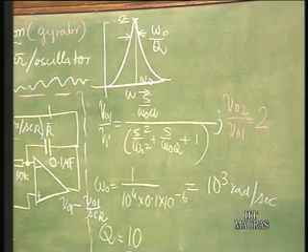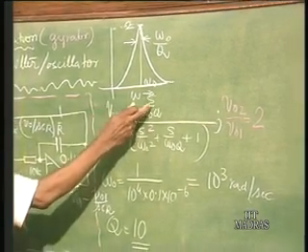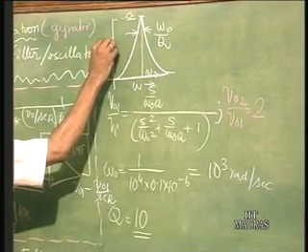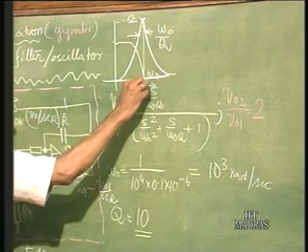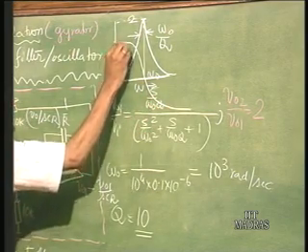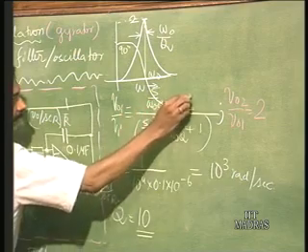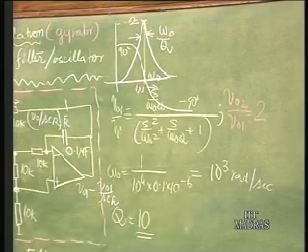Not only that, if I plot the phase shift, okay, initially phase shift is due to only S, that means 90 degrees, and then the phase shift is going to become 0 at omega naught and goes to minus 90 degrees at very high frequencies. So, phase shift also is going to 0 at omega naught.